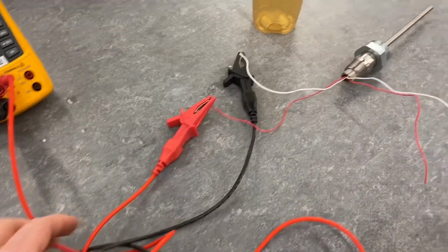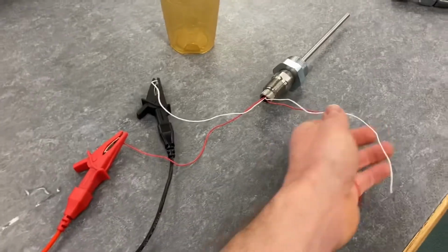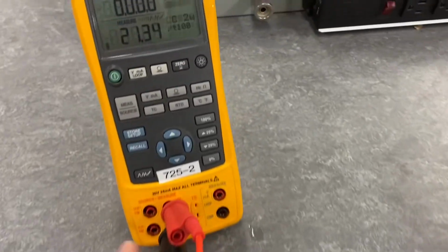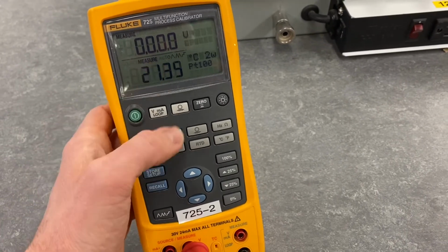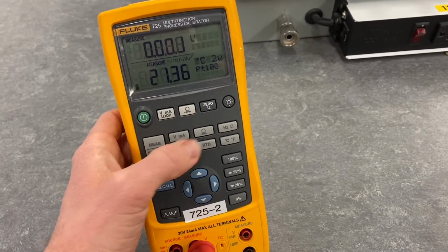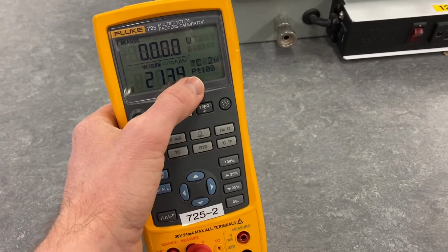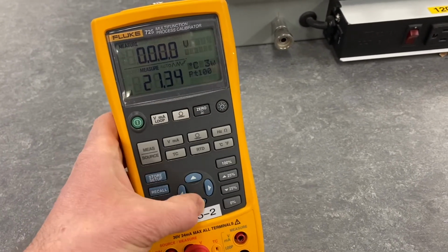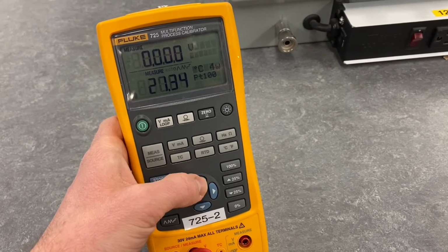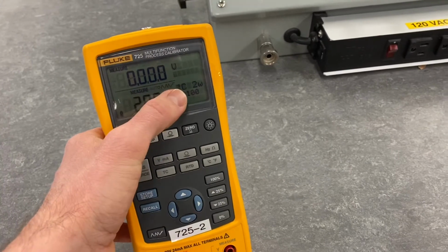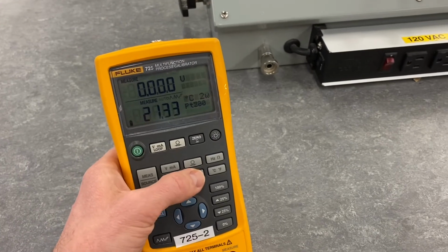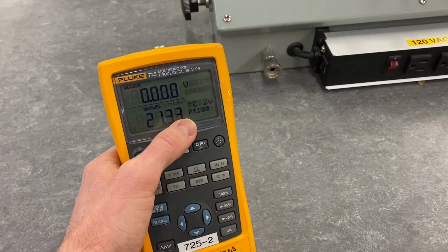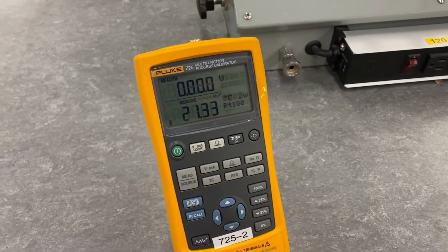taking our RTD that we used here, just connecting up with 2 wires, 2 leads running over to our Fluke here, and we're going to have it set with this toggle. Then we need to set this to measure, like it just was, and then we also need to set the RTD to platinum 100 right there, and it needs to be set for 2-wire. If you move these up and down arrows, you can change it from 2, 3, and 4. It needs to be set for 2-wire, platinum 100, and it will read 21.33. To toggle between the RTD, we push this button until it says PT 100, PT standing for platinum. So it's at around room temperature, not bad.